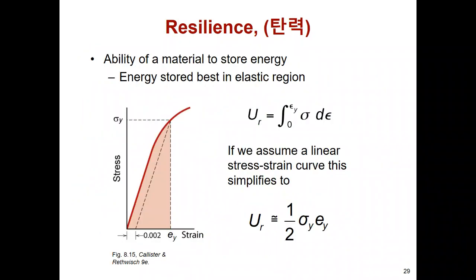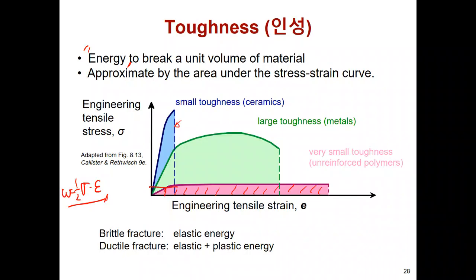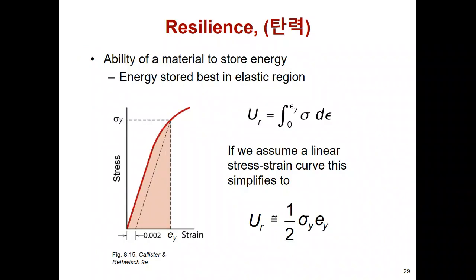Next concept is resilience. Resilience is the ability of the material to store energy. In the previous slide we discussed toughness, where most of the energy comes from plastic deformation. The elastic deformation energy is very small. When we deform a solid material, this solid structure has a higher energy due to the work done by forces. That amount is the resilience.